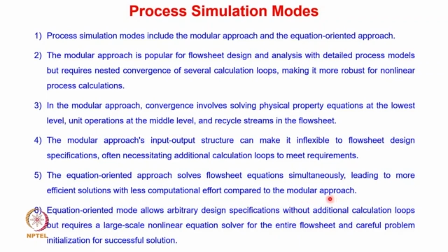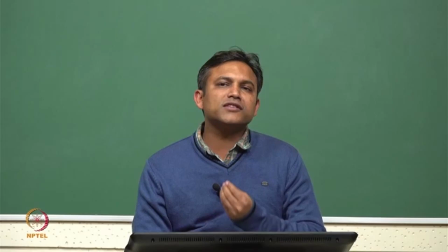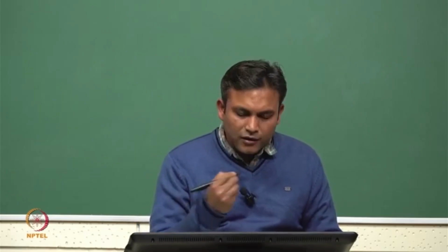The problem with the equation oriented approach is primarily the convergence. If there are several non-linear equations, typically we use non-linear equation solvers, and all the non-linear equation solvers require starting values for the problem, isn't it? Typically the convergence depends on what starting values we are using, and how accurately and efficiently the non-linear equation solver is solving the problem.